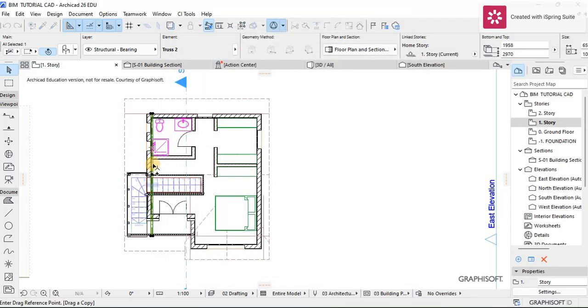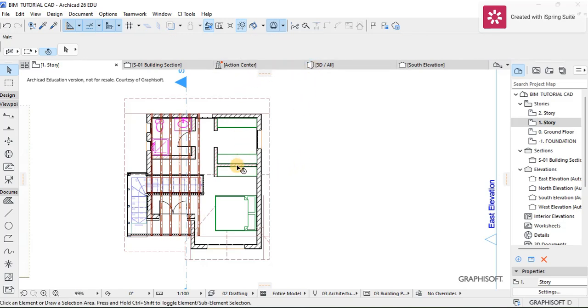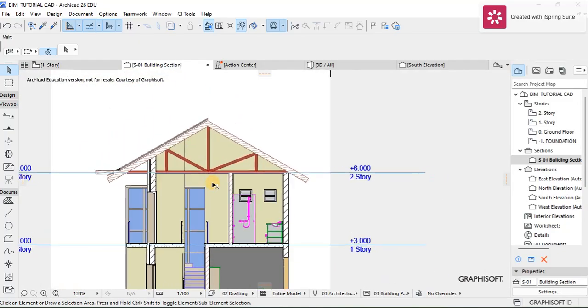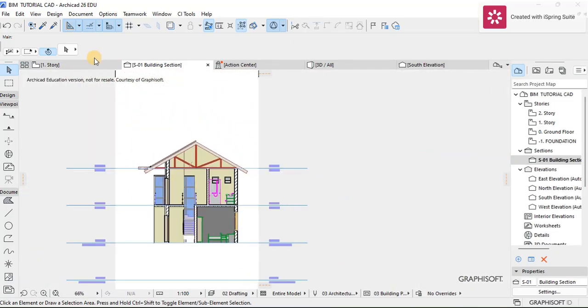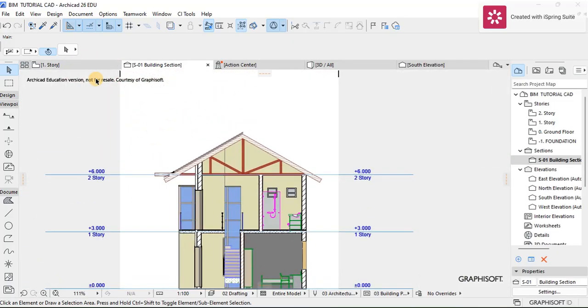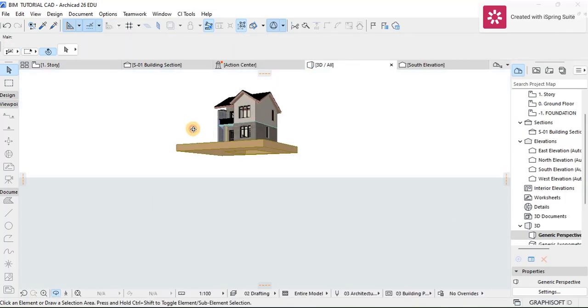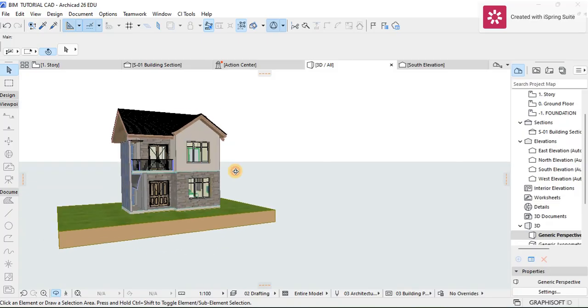So I'm going to drag copies across where everything is going to be. Actually, it's going to end here before we encounter the other gable, so it's going to be there. Yeah, something like that. So this is what's going to be holding our roof. You see in the 3D section, there are going to be more of them, just more of them like this. So you do the same for the other gable. And with that said, on that thought, we can say that we have finished building our building, and now we can just extract information from it.